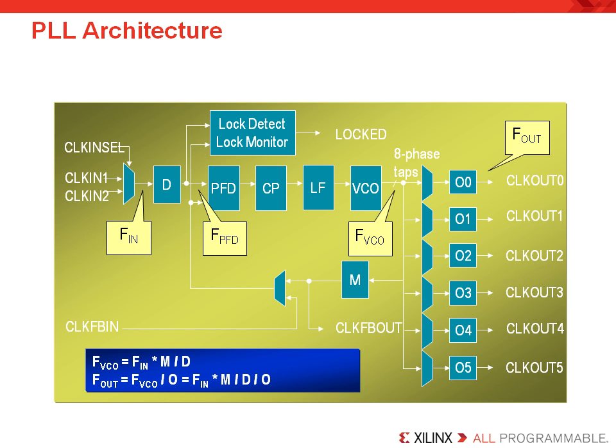Please note that as a division occurs, the duty cycle can vary, but the division will be correct. Static phase shift amounts can also be set independently on each MMCM output. And you can use the dynamic phase shift port, which will adjust the phase shift on all MMCM outputs, in addition to any static phase shift amount that is configured on each individual output port. So there's a lot of phase shifting functionality here as well.